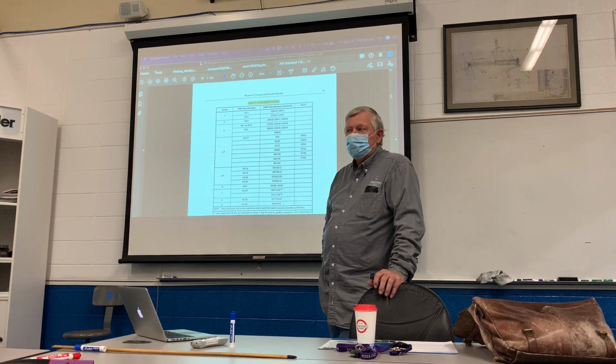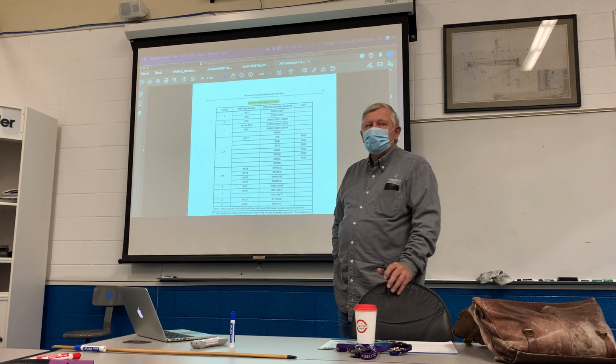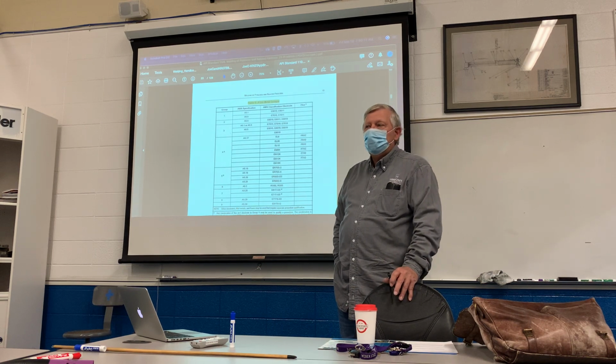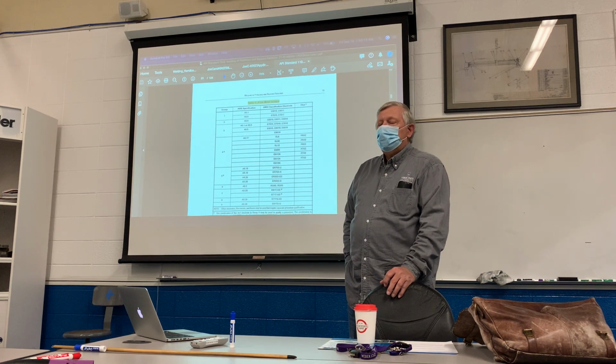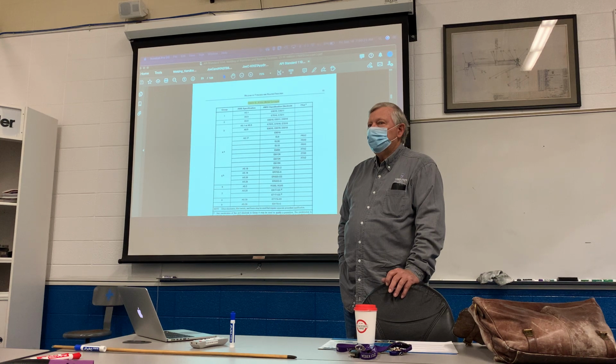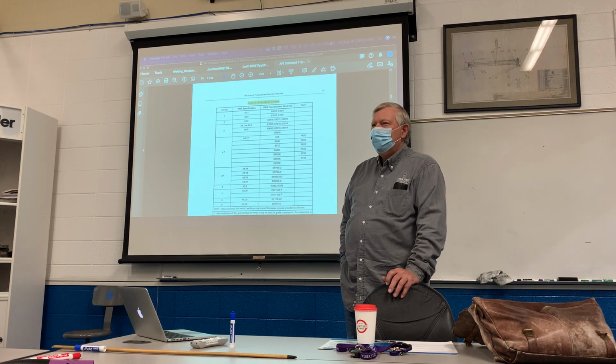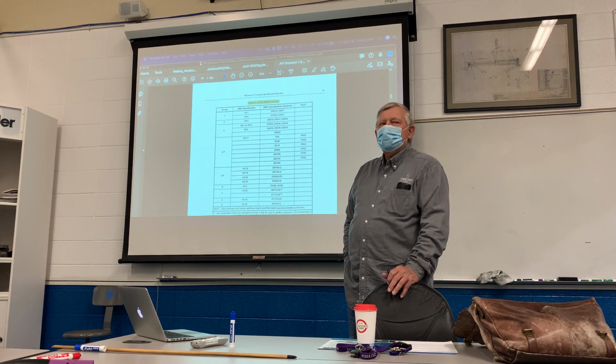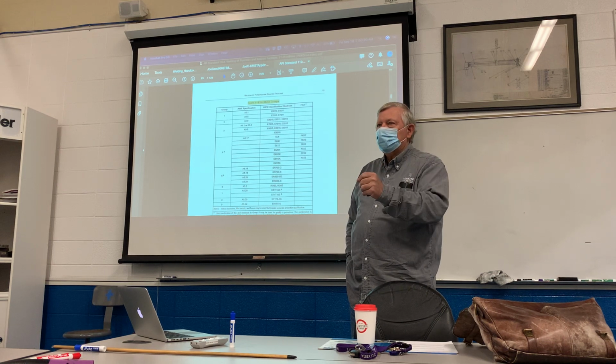Yeah, he can. If the preheat in the procedure says 250 degrees plus or minus 50 degrees, what does that mean to him? 200 degrees. Yeah, and 200 degrees has to be when he strikes the arc.